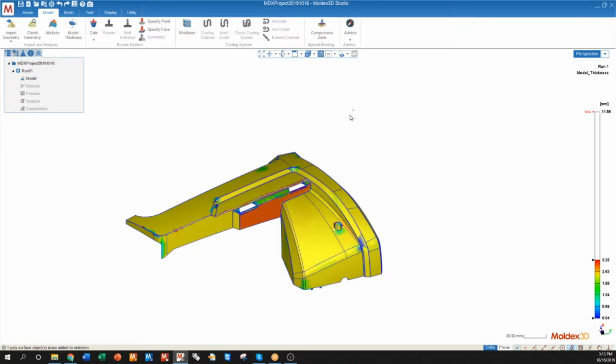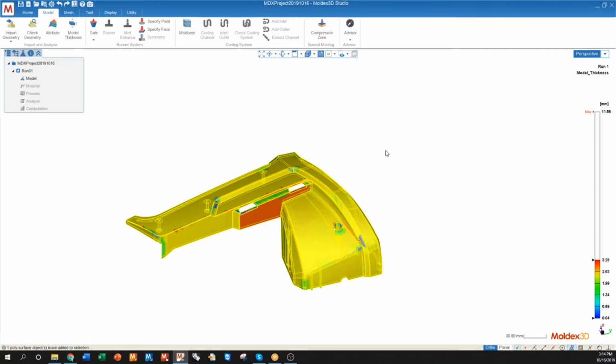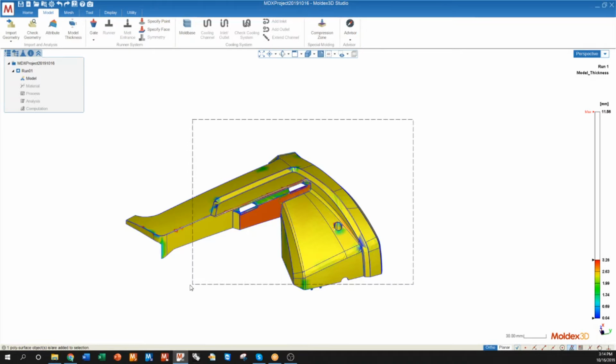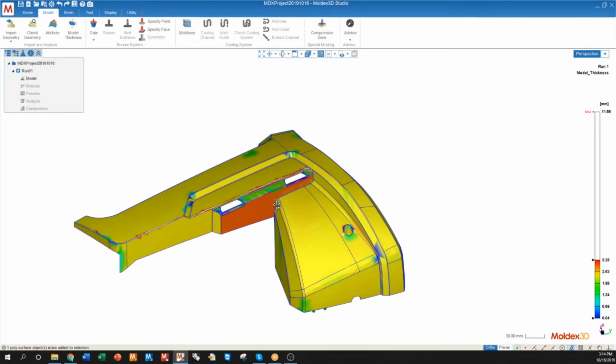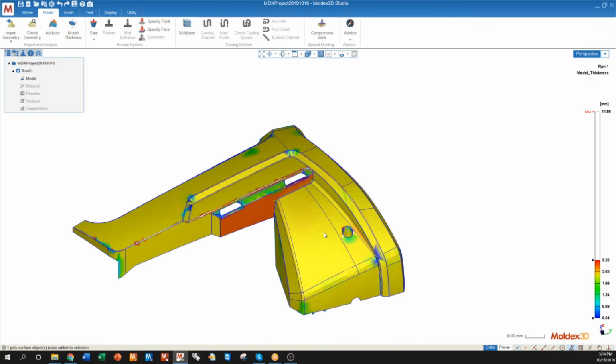Going from right to left, however, anything that interacts with this box is going to be selected. So whether it's completely contained within the box or only partially contained within the box, it will still be selected. Both those box selects can prove quite useful under certain scenarios.